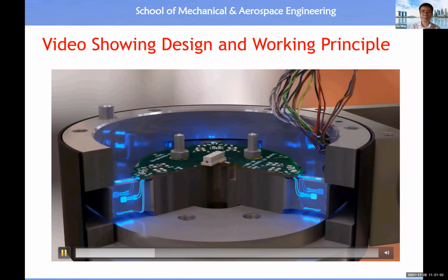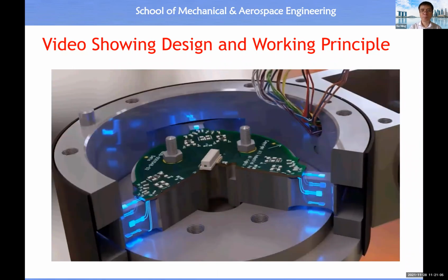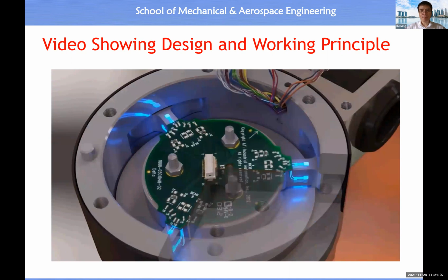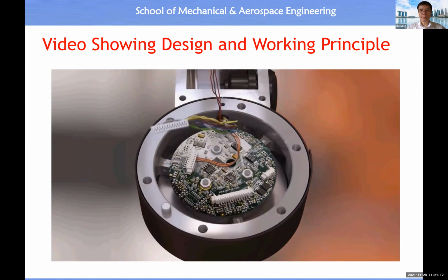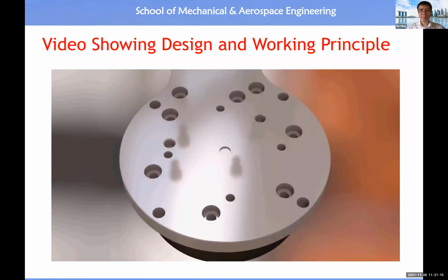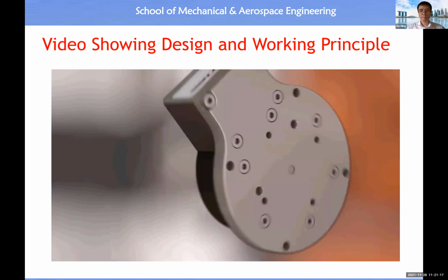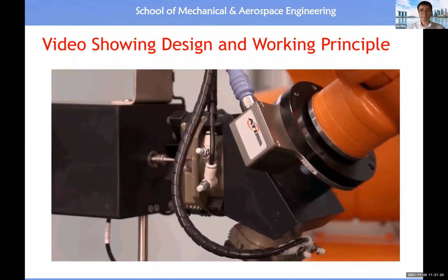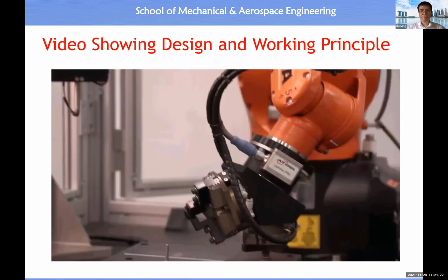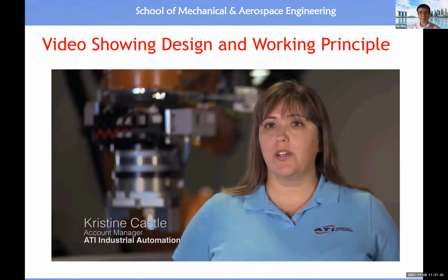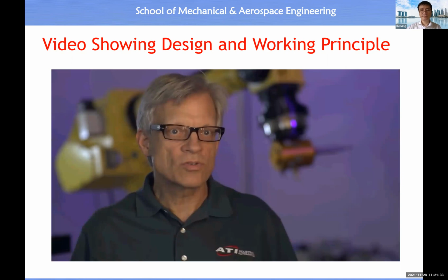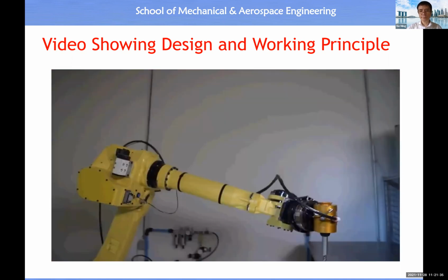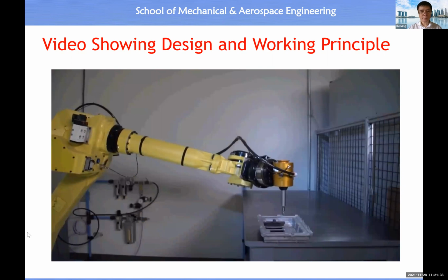The high gain in the strain gauges allows the beams to be extremely strong, providing very high overload protection. Proprietary bonding methods used during the mounting of the strain gauges greatly reduce hysteresis, which can be a problem for load cells. The benefit of using a force torque sensor versus a single axis load cell is that you get a complete picture of everything acting on that transducer instead of just one snapshot of the measurement. The ATI sensor can measure loads that are applied in any orientation on any axis.